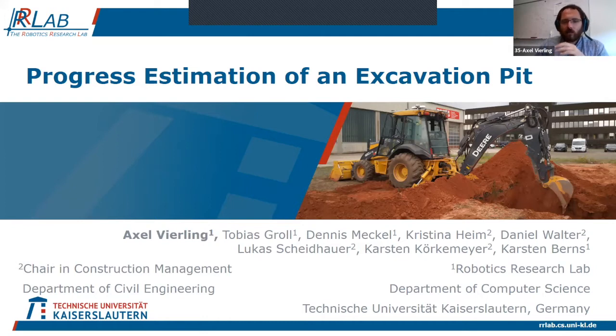But what does this really mean? We don't want to estimate only the current progress with respect to the volume or the mass, but rather with respect to the performance or the current speed, how fast we are excavating. Of course, the deeper the trench is, the longer we will take to do the next excavation step. Or if the soil conditions are different, then we might take longer than at another part of the excavation pit. So we want to take this into account. So it's a progress estimation with respect to the performance or the speed.